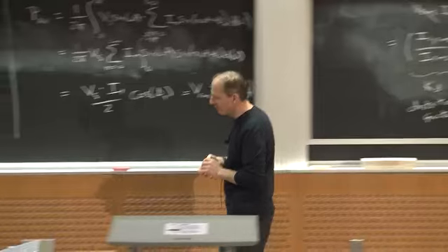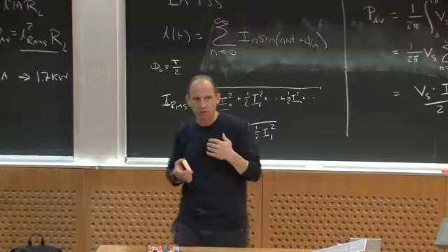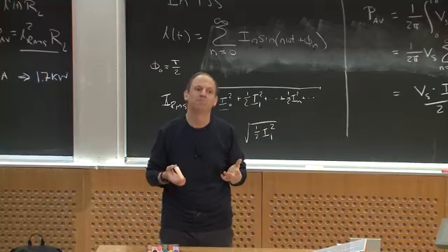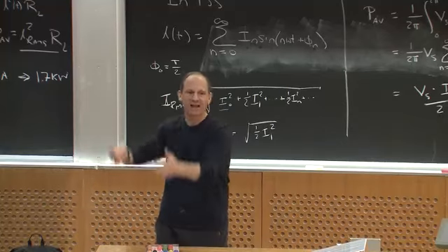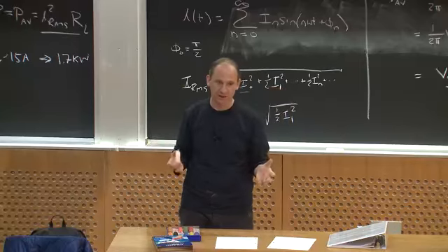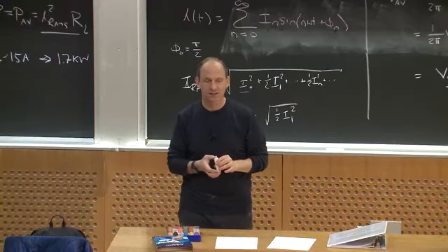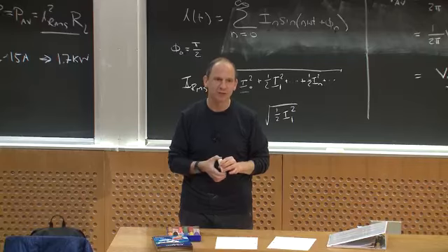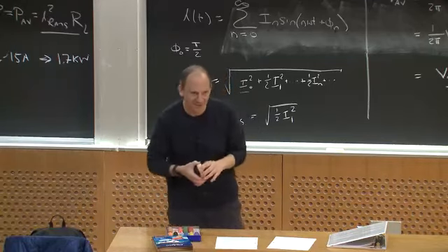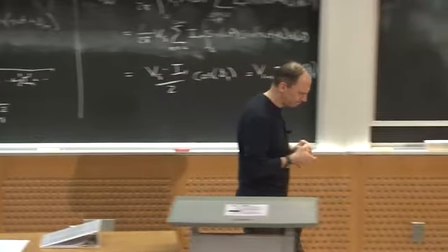Yeah, that's a very, very good question. The answer is, if you are an industrial user of power, right? If you're running a big factory that's drawing lots of electricity for whatever your industrial process is, yes, the utility can come and say, you've got to clean this up. Or what they really do is they start charging you if your power factor is not good enough, right? And then you go clean it up because you don't want to pay them. All right? So that's one way it's limited.